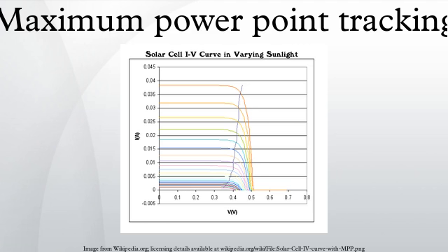IV curve. Photovoltaic cells have a complex relationship between their operating environment and the maximum power they can produce. The fill factor, abbreviated FF, is a parameter which characterizes the nonlinear electrical behavior of the solar cell. Fill factor is defined as the ratio of the maximum power from the solar cell to the product of open circuit voltage VOC and short circuit current ISC.